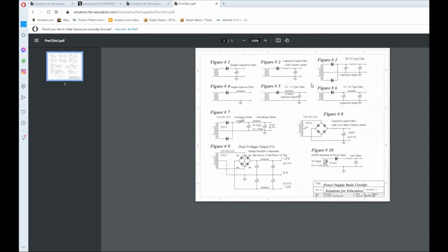The control amplifier that I worked on aboard ship, I was on the repair ship, ran on 800 volts. And what that amplifier did is it controlled the amplidyne that controlled the gun mounts. And you could make those gun mounts move so fast that if you were in the gun tub in an area called the dead man zone, you could not move fast enough.